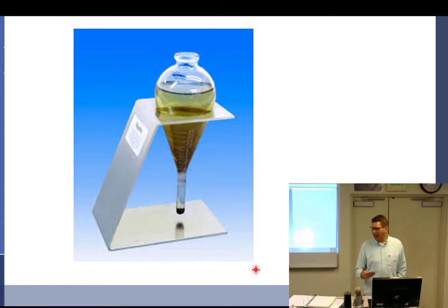That's something I did every single day. I think if you ran shifts, you'd have to check it every shift. There's actually quite a bit of carry-off with this. Carry-off is where the particles are on the part, and then you take the part away. You guys are starting to notice our bench getting piled up with the iron filings. So periodically, before I would just add more media to the bath, I'd actually clean my Magnaflux machine.